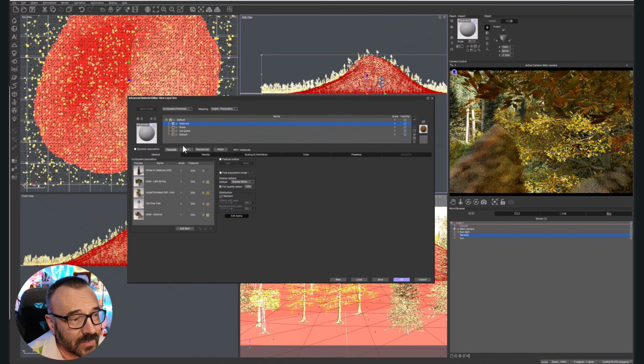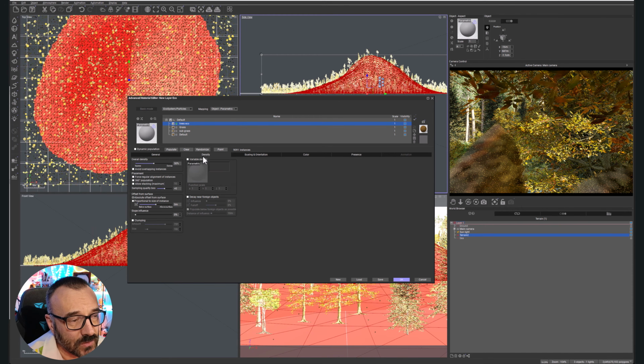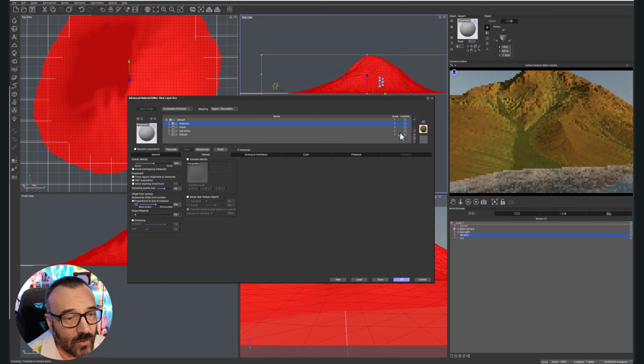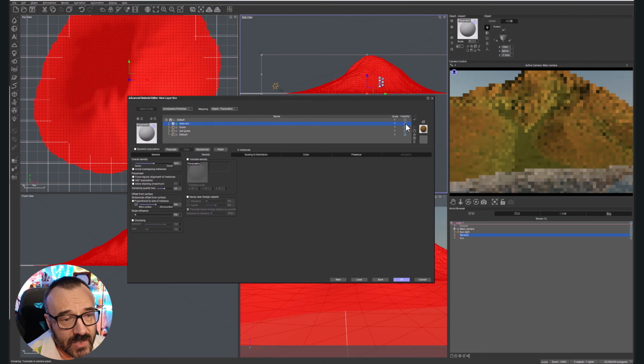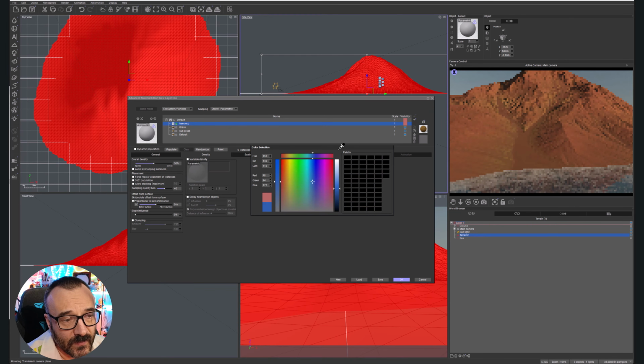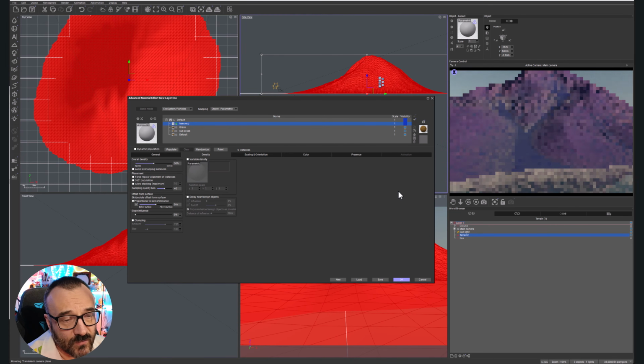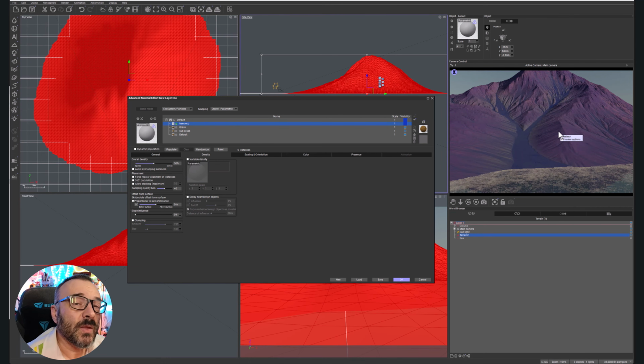And here come our density controls. So let's click on the density, and notice we have variable density. We have other elements, scaling, all this stuff. So let's play with this. First, what I want to do is see where the plants will go. For that, let's clear our plants, and we'll also enable the highlighter. And I'll just switch the color for this highlighter. So this is showing me where those plants will be populated.